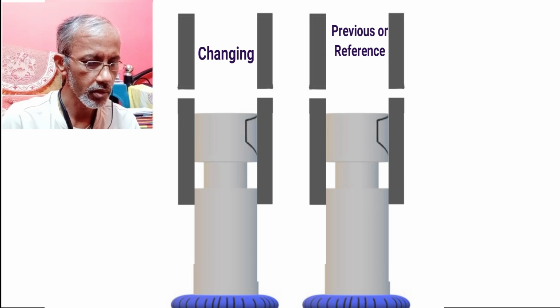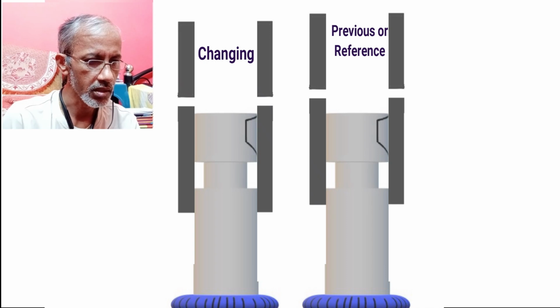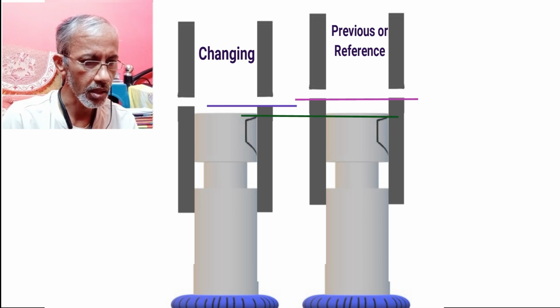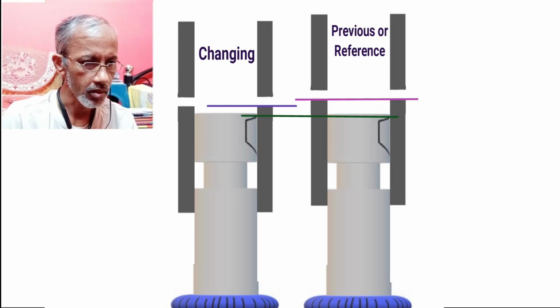So when we lower the barrel position, let's say we take it to this point, it is clear that the time that the plunger will take to start delivering the fuel is now less than the one where the previous position of the barrel was there, because as the barrel has been lowered, the distance between the upper edge of the helical cut of the plunger and the position of the port is now less.